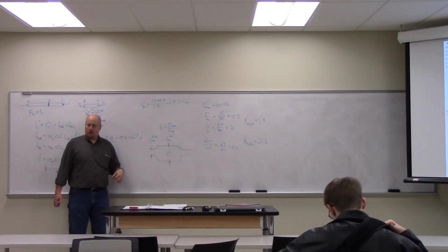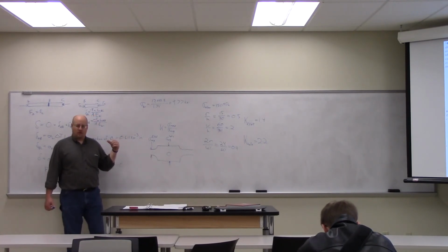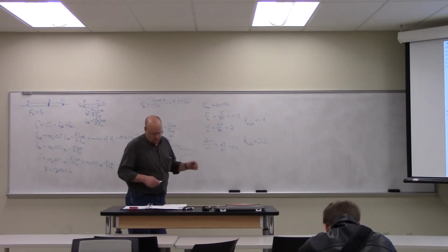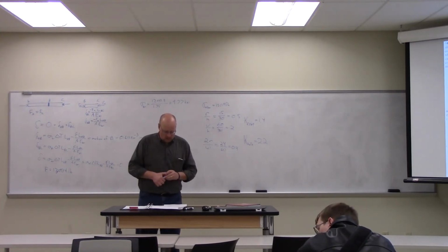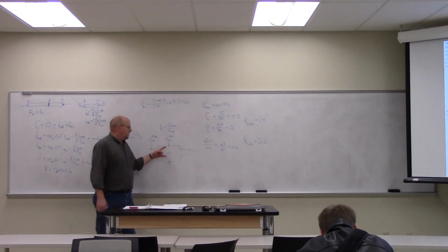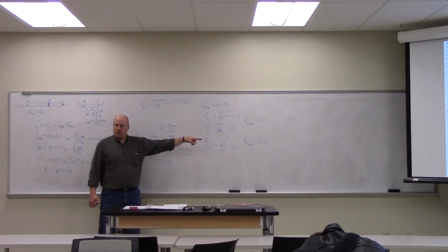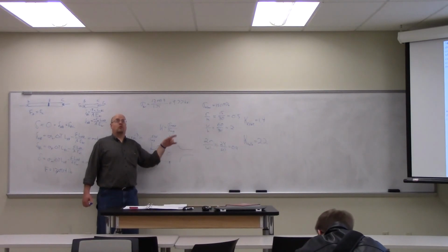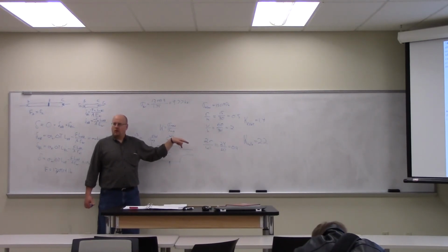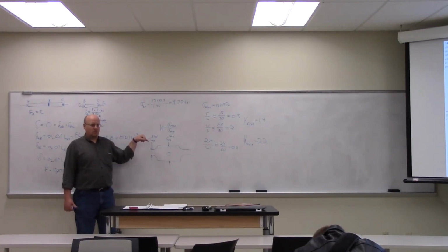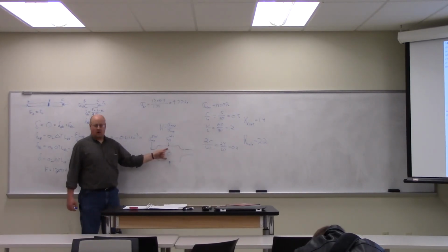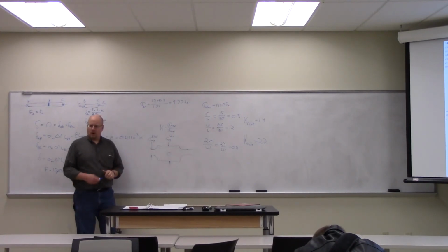Now, it turns out the hole is still going to be the greater stress concentration, but that's just a guess, right? Well, I've got the numbers in front of me, but 2.2 divided by 36 is still going to be a larger number than 1.4 divided by 30. See what I'm saying? That one's 1.5 times as big. This area is not 1.5 times as big. So I know the K factor is going to be the biggest contributor.